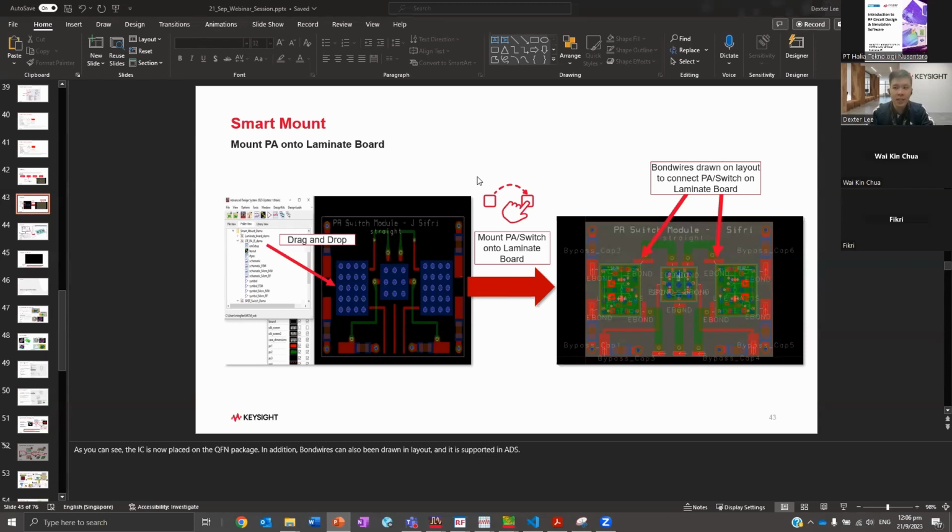We also have a stability analysis called the WS probe, which I won't go through today. If you want a comprehensive stability analysis, because when we talk about stability analysis, it's not just K factors. There are so many stability approaches out there in the industry. So the WS probe is one tool that I don't think Virtuoso has.